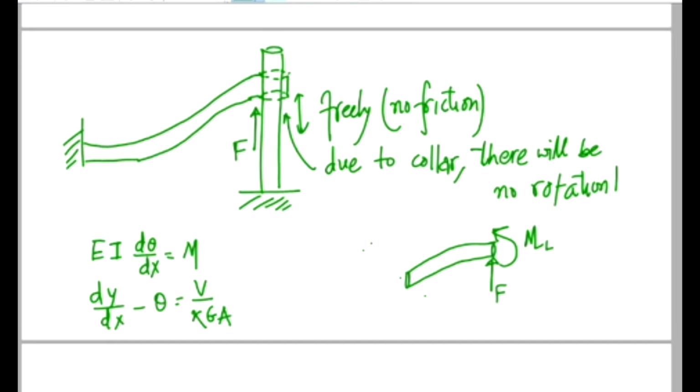Likewise, you see there is no axial displacement allowed at this end because it is adhered to the rigid pole, and this pole cannot move axially, isn't it? This pole cannot move axially. So even this end of the beam cannot move axially. So that means the pole must exert a force in the axial direction on the beam, right?